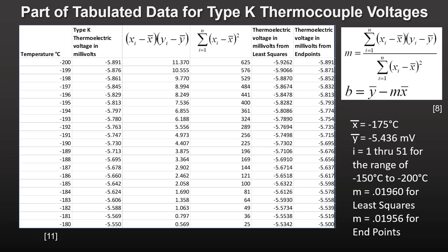We use this method 49 more times, and we find that the millivoltage calculated at minus 150 degrees C is exactly per the table published on www.nist.gov. These data points are shown in the far right column. Only the endpoints are equal to the actual thermocouple voltage. The points in between are another linear approximation of the nonlinear thermocouple curve.